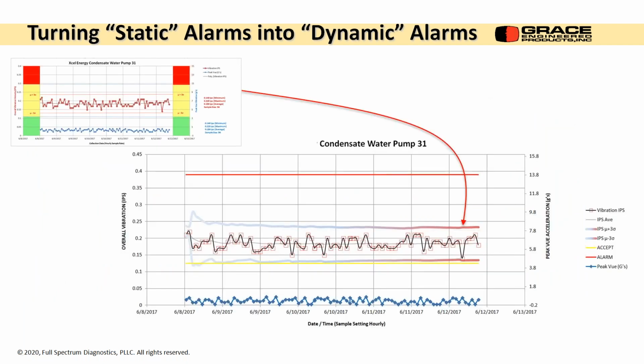But this is what you can do with the single point wireless transducer. You can take that data and you can get, this was 94 measurements. This was 1 an hour, and I can see massive statistical changes. The gray was initial, the first couple hours, it's pretty ragged, and then all of a sudden it starts zeroing in on a much better statistical alarm level.